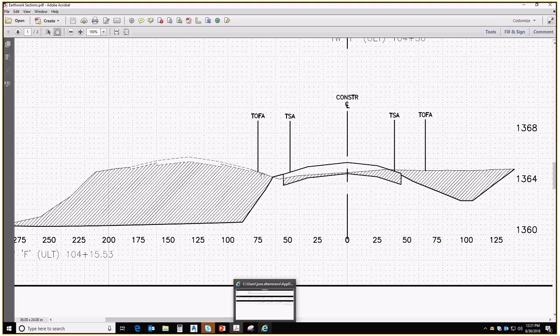Look at your slopes and, sometimes we have typical sections, make sure the slopes are falling within your typical sections' control criteria and the widths and offsets are correct based on your design. Then the next thing you want to do, going back to what we said earlier about best practices, is make sure your subgrade line is correctly modeling the subtraction for your paving section.